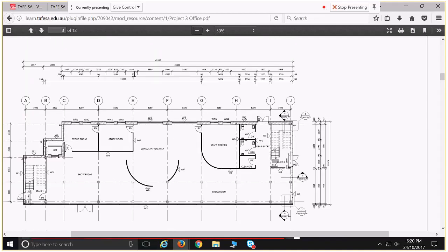Also, just a quick note about reading dimensions. The closer the line of dimensions, so here we have 1, 2, 3, 4, 5 lines of dimensions, excluding our grid lines. These dimensions back here, the first one relates to, so we've got 265 here, and then a large space to a 90 wall there. So this set of dimension lines relates to this plane cut straight through the building.